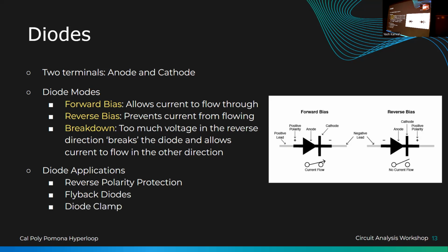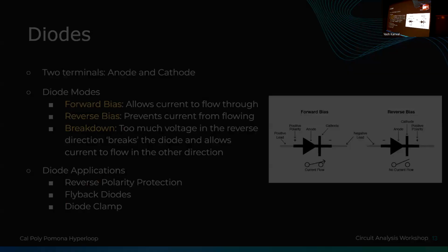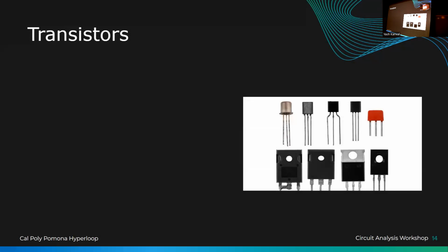But funny story, actually. When I designed Wiki-Learner 1, when we did the first ever soldering workshop like 2 years back, I forgot a reverse polarity protection diode in the circuit. So about 30 or so kits did not have one. If the students, when they were building the kits, swapped the red and black wire, the 555 timer would just blow up. It would start smoking.